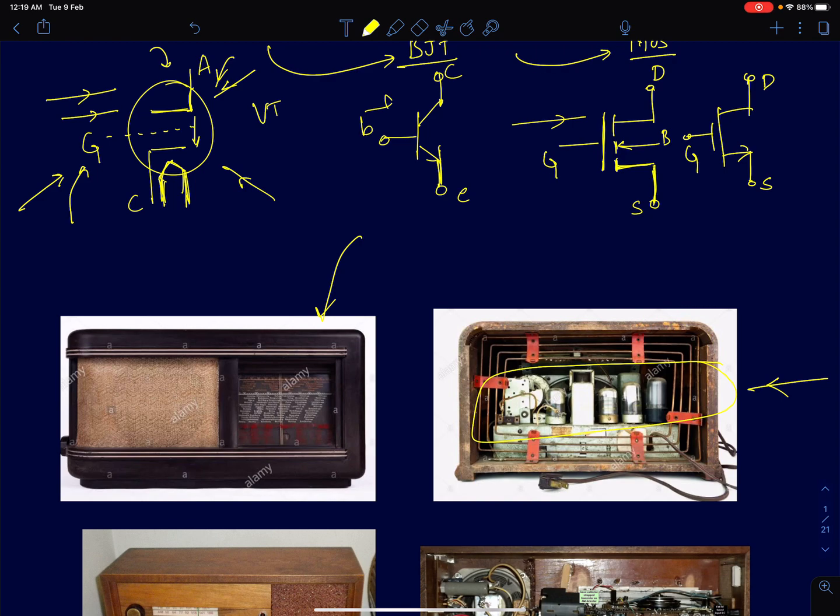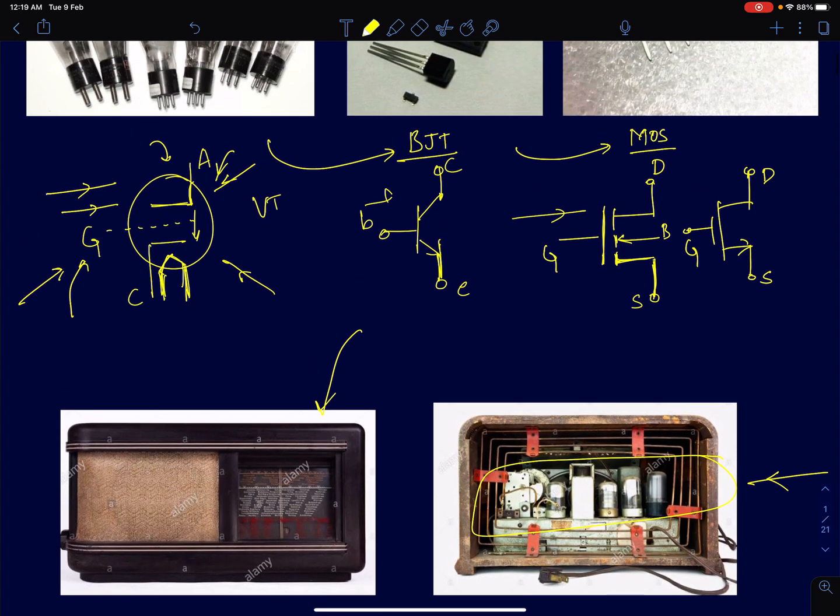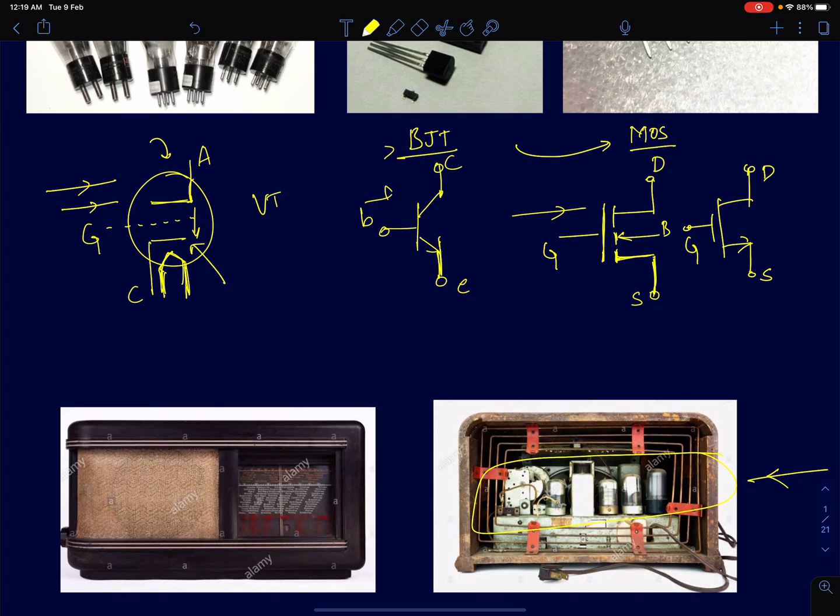One problem that engineers faced with vacuum tube amplifiers is that the fundamental principle on which a vacuum tube amplifier operates is thermionic emission. First you have a terminal called the cathode. You generate electrons on that terminal by heating it. A separate coil is used, a huge voltage is applied to this coil, and the coil is heated by I²R losses. When you heat this coil, it emits electrons by the process of thermionic emission. These electrons are then drawn towards the anode, or the positive plate.